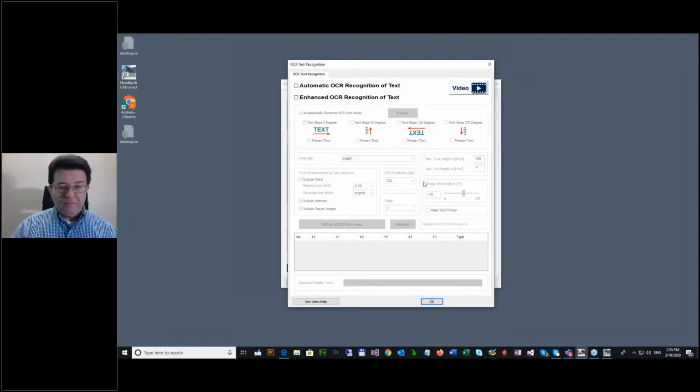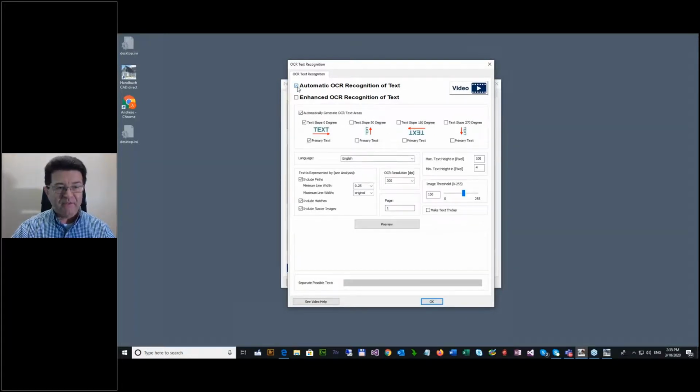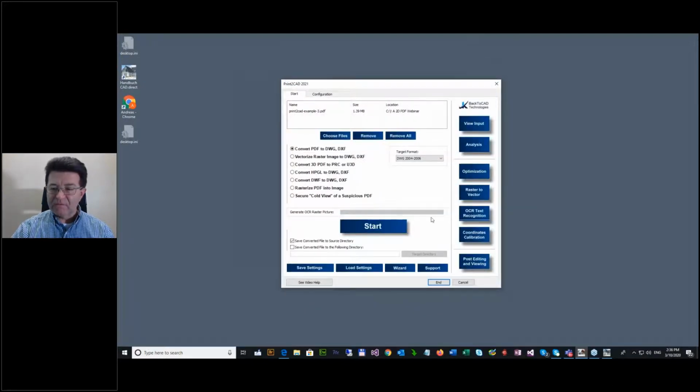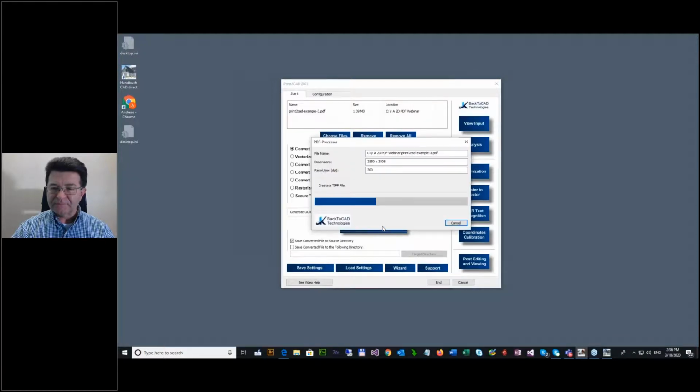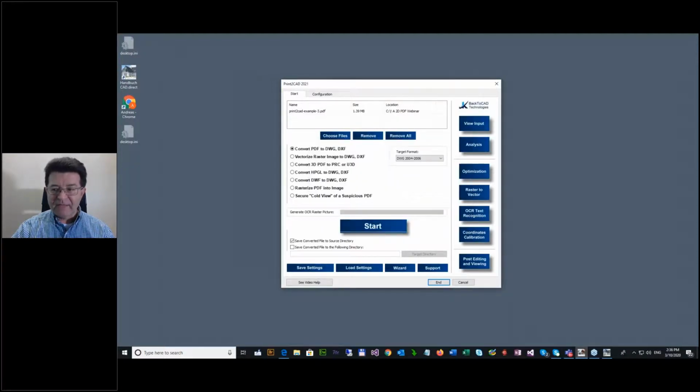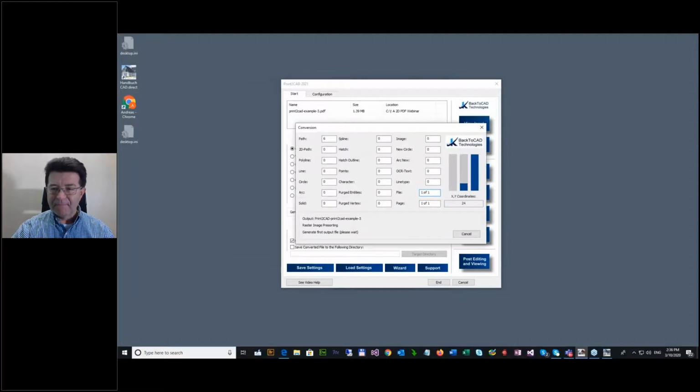And you can use two kinds of artificial intelligence text. Full automatic text. My text is only horizontal, and my text is a raster picture. Language is English, United States, and now you see automatic, 0 degree. I don't have vertical text, primary text, and raster. And let me check it. Now what's going on? Now we start the raster to vector methods and optical character recognition.